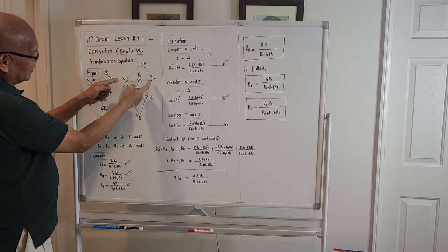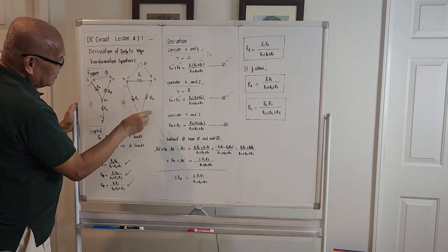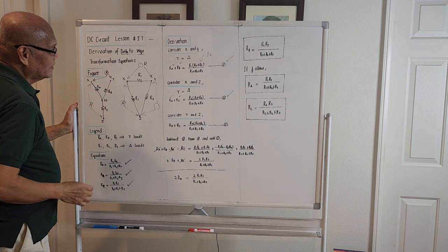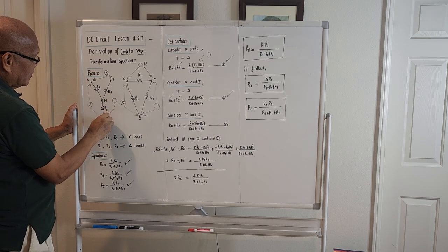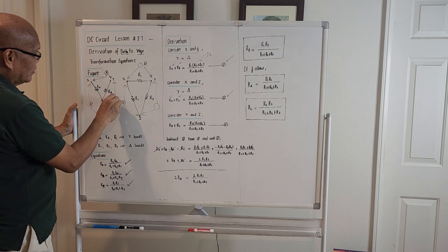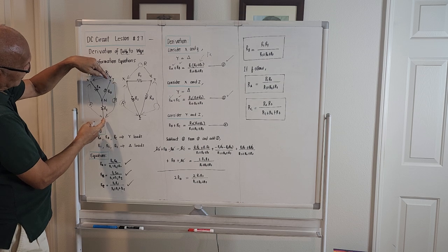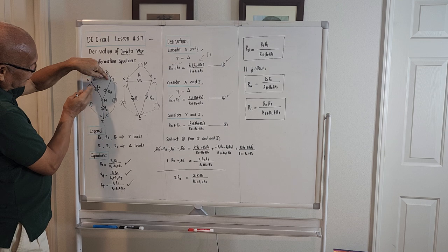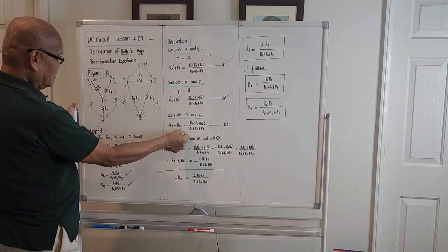So we are done with the terminals X and Y, X and Z. We will go with the terminal YZ. We'll get our tester here. We tap it here. Okay. We'll do first Y. Okay. We'll take the resistance. We are on the terminal Y and Z. So if we try to tap our multi-tester here, RA will be an open circuit, so it will not be included in the computation. So the total resistance of the reading should be the sum of RB plus RC. So this is RB plus RC.